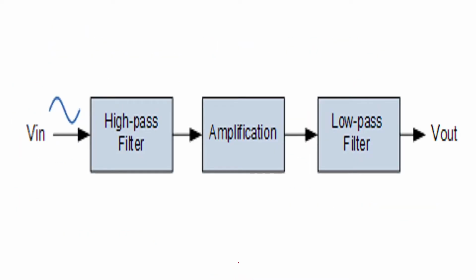Then, if you look at the bandpass filter technique, you can realize a bandpass filter by using a high pass filter and a low pass filter. So here, as we have shown, the input is first connected to a high pass filter. This high pass filter will be a passive high pass filter with a capacitance in series with the input, and then a resistance in parallel with the input, and here you get the output. So this will be your input, this will be your C1, and this will be your R1. This cutoff frequency will be your FL, which will be equal to 1 by 2 pi R1 C1.